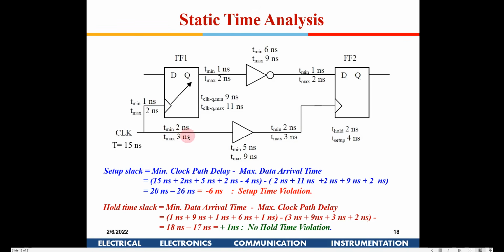I am going to take the maximum one, because I am computing the slack now. Setup slack means I am going to find out the worst case scenario, and for the worst case scenario, I will take that the clock is arriving fast and the data is coming late.